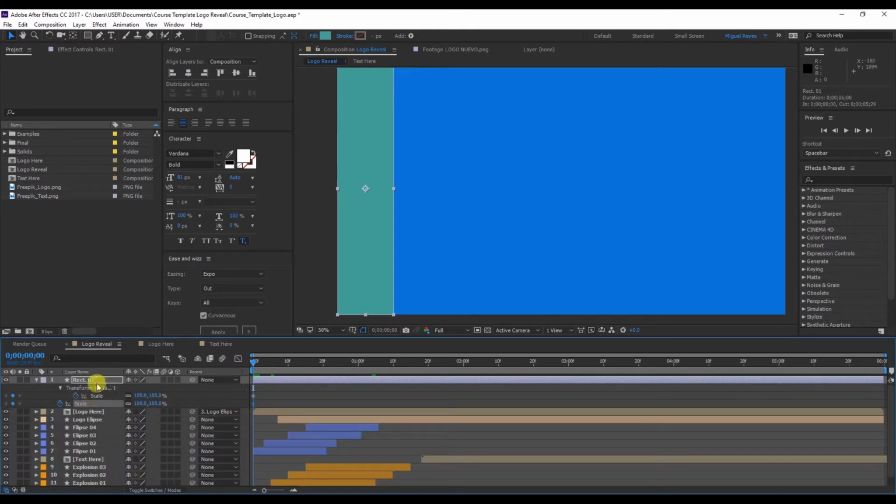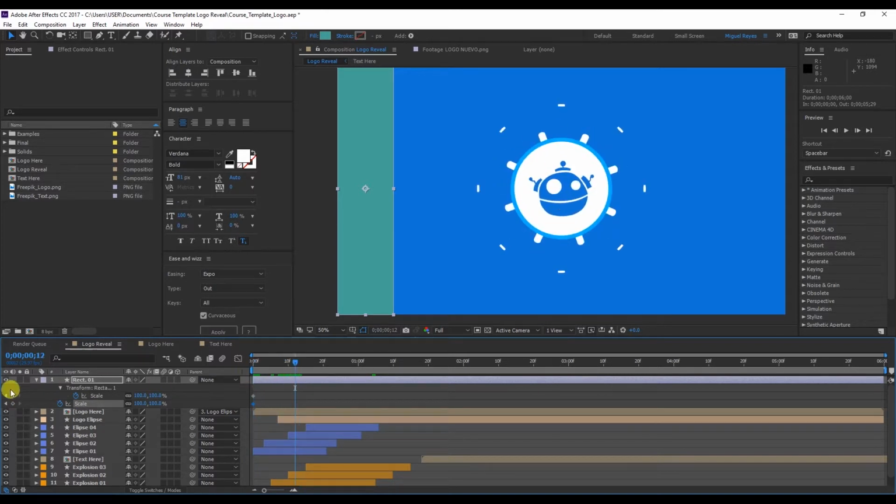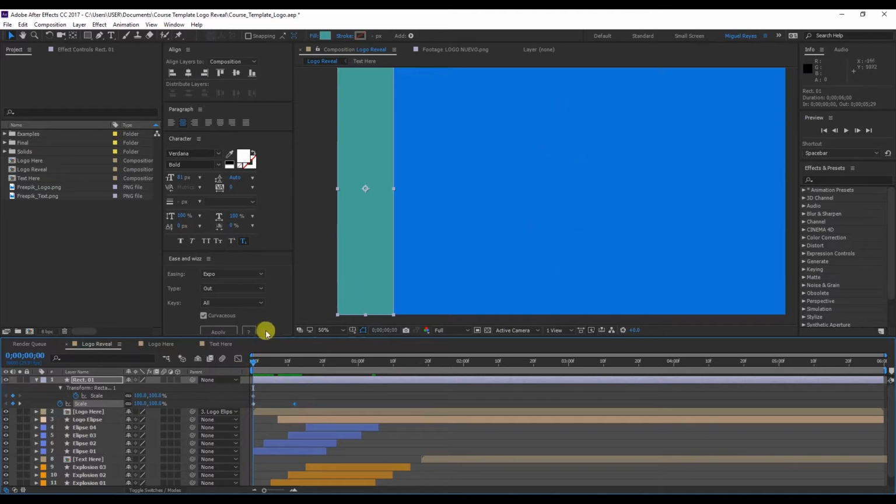Press U and you can see both scales. On the lower scale, go to frame 12 and click to create another keyframe. At the beginning, we'll do the following. First, remove the chains from both of them and put 0% for the height. But if we do this, see that the height depends on the anchor points being in the middle. But I want to reduce the height quite a lot based on this point.